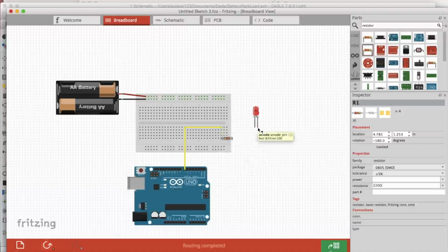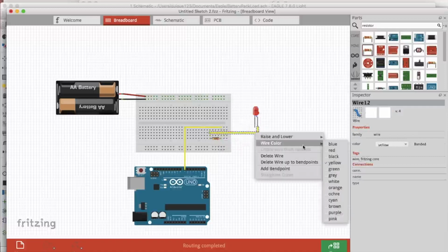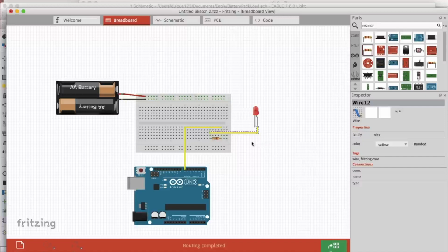resistor. Actually going to keep it in this orientation. And place it over the breadboard. Don't drag from the components. Move it over the breadboard. Hover over the breadboard, and once you get the circle icon, then you can drag a wire out of there and connect the component to it. Alright,